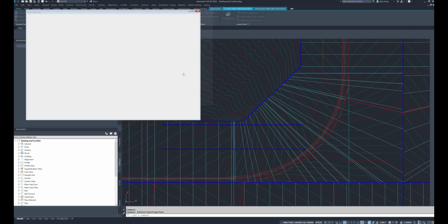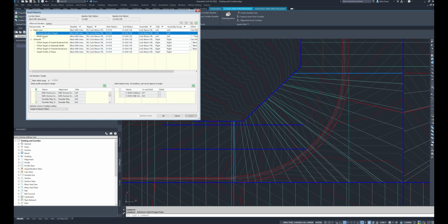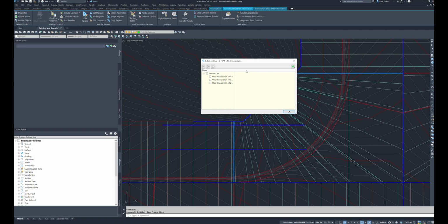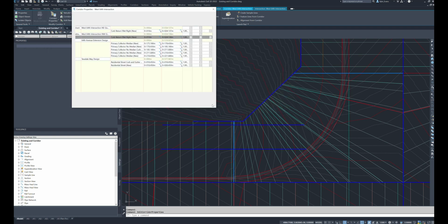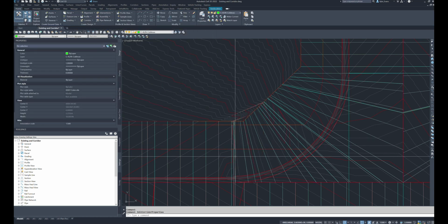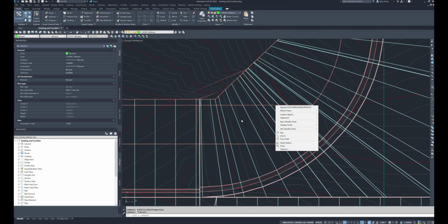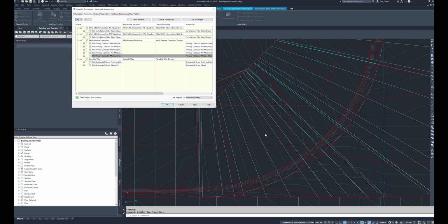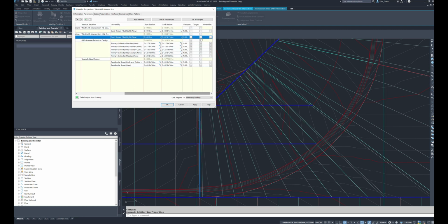Under that target, we have elevation, we have width, and then target profile of slope for the sidewalk. So let's try and see if we can tell the sidewalk to follow that inner feature line for an elevation. Nope, it seems to have made it a little bit worse. So again, make an alignment, make a profile if you really want to control the elevations. We could come in here, and actually let's do that quickly and we'll wrap this video up.